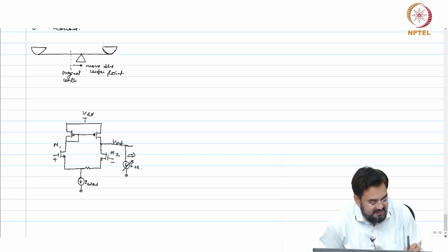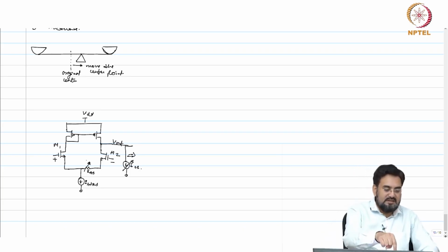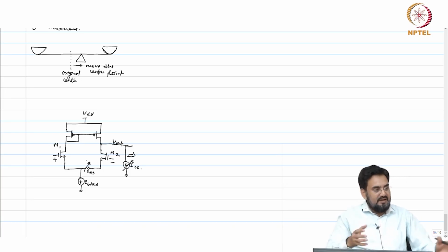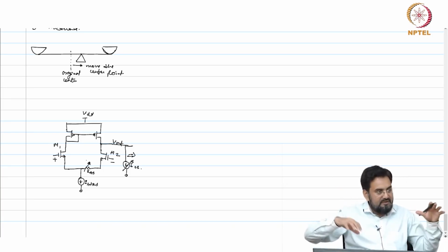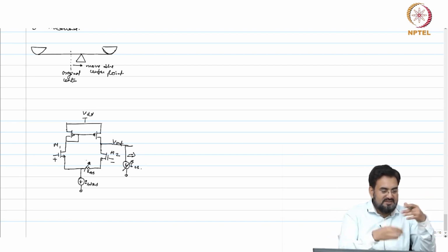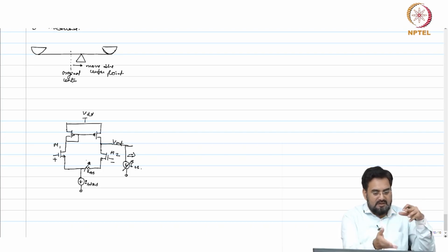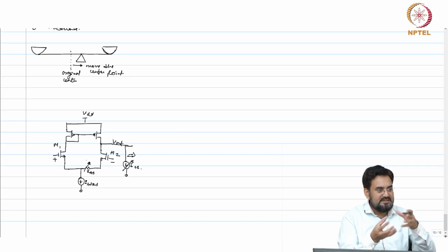This is the technique we most often use, and this is variable. The reason we use this technique is that when we already talked about the placement of M1 M2, you try to match them. Matching means the offset is very small, not that large. So you cannot further break those pieces into very smaller pieces. There is some limit there.